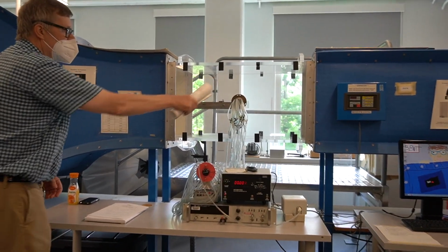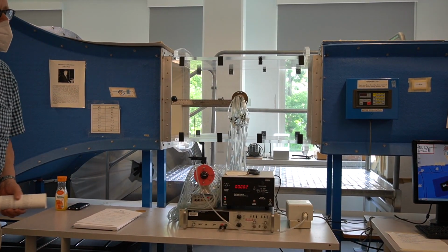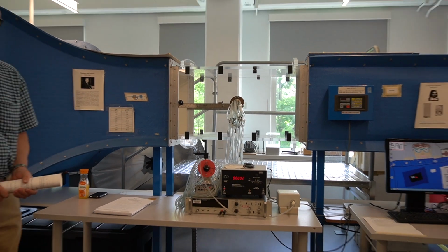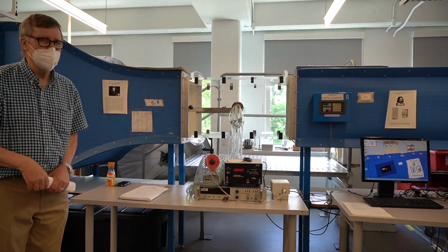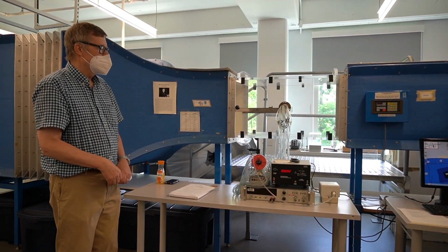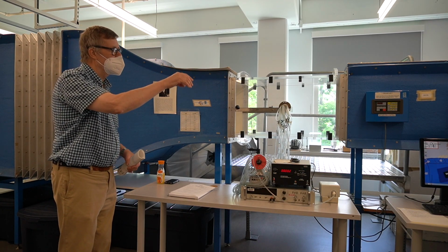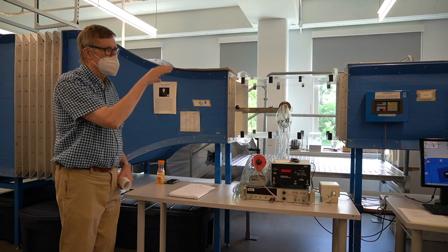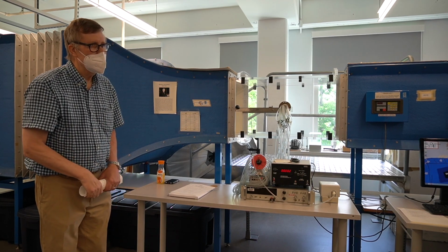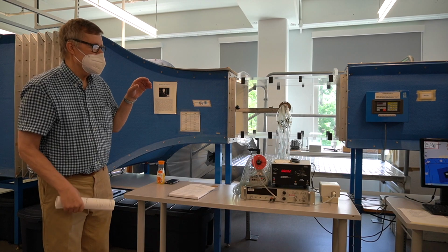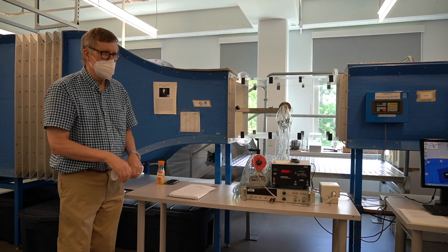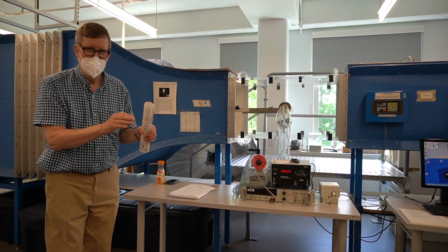So flow is going from left to right. The thing about this wind tunnel is it's different from other little tunnels you'll see in FM2, in that you have the motor downstream, and you have a centrifugal fan, which is basically, it's not blowing the flow down. This wind tunnel sucks.